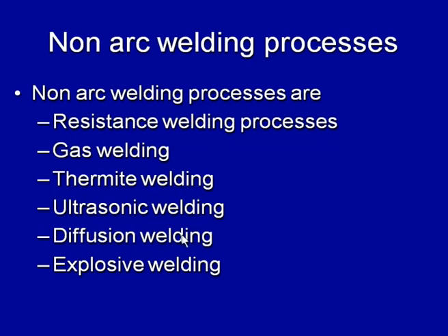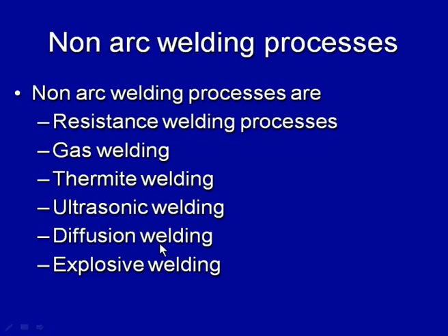the members to be joined, and for this the components to be joined are kept under firm metallic contact at high temperature for long under pressure, so that the diffusion across the interface can take place from one side to another, and they get a metallic continuity.